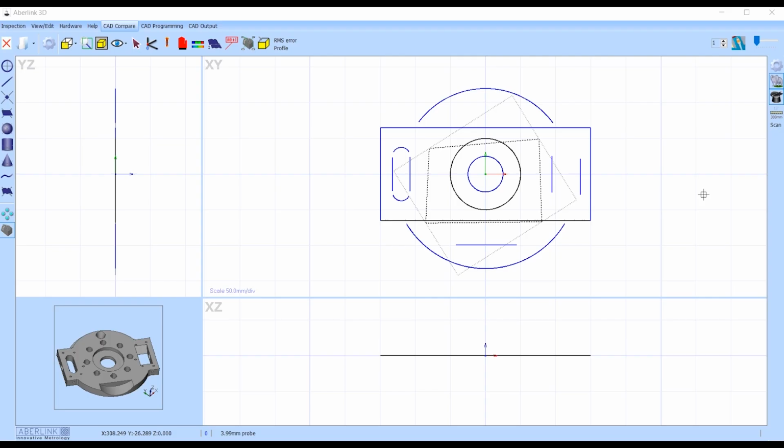Okay, another handy function within Aberlink is the CAD comparison with deviation tags. Along with the traditional probing and reporting routine, Aberlink is able to quickly compare the CAD model to the actual machine part, probing selected positions and getting a live deviation tag representing the distance from probe to actual CAD model distance. When full inspection routines are not required for high repeat orders, asking for 1 in 5 or 1 in 10 inspections of parts is sufficient.